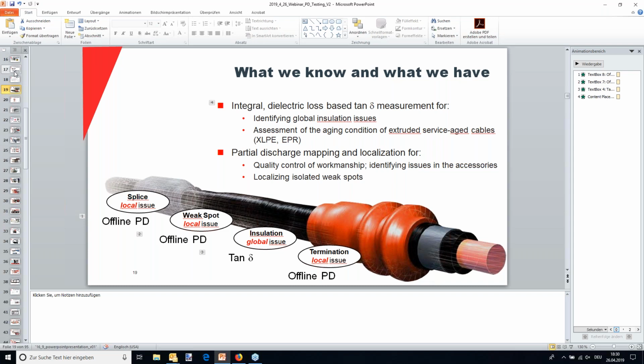And PD in cable itself, as I said, you would have to have what's called a field intensity related fault, which is the voids, which are very rarely seen these days. The manufacturing quality of Nexans, Südkabel in Germany, Prysmian, General Cable, well, that's Prysmian now. Prysmian purchased them. At least in Europe, I can say we rarely see these defects anymore. I'm not entirely sure if it's the same over here. I'm hearing different things, so I'm not willing to make a statement on that.